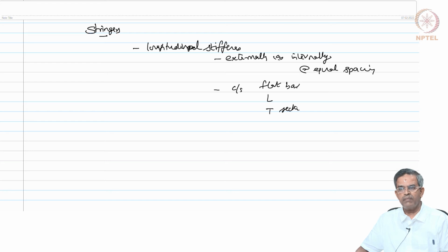Now, the structure is fabricated from hot or cold form plates. Essentially, the welding will be a butt welding, and therefore, we need to check whether the stiffened cylinders are stable for a given configuration. The geometric distortion and residual stresses are some of the common problems which you have heard in steel structures which commonly occur under welding process.